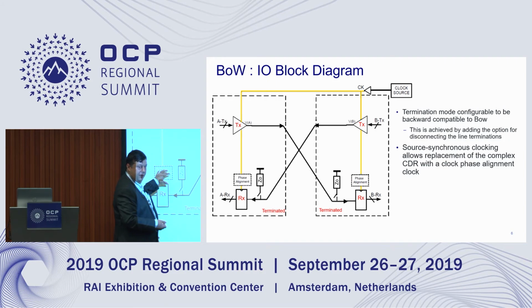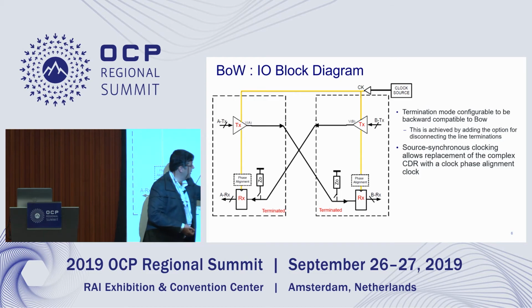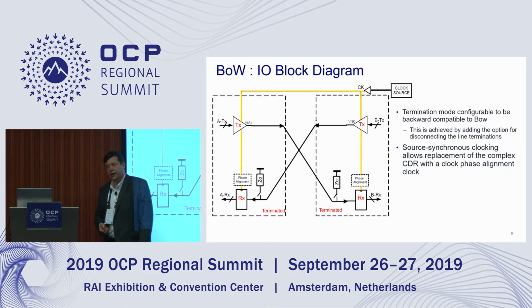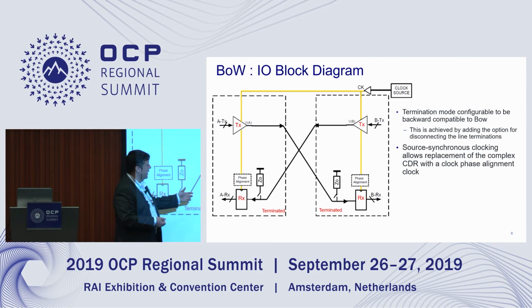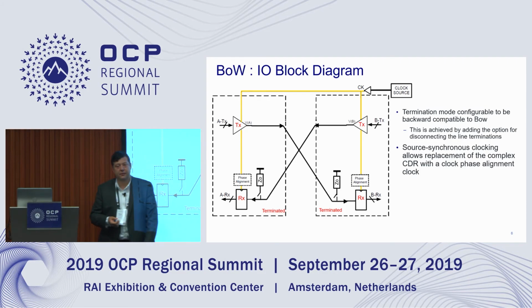We adjust the clock so that we can capture data on the RX. So again, very simple source synchronous interface with selectable termination in the case where somebody would want to be enabling the terminated mode for the interface. So you can turn it on and pay a little extra power to go faster, essentially.